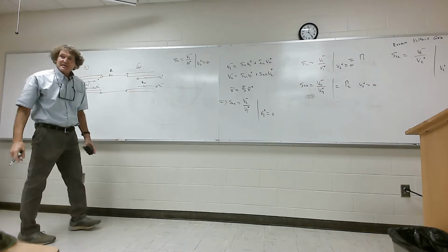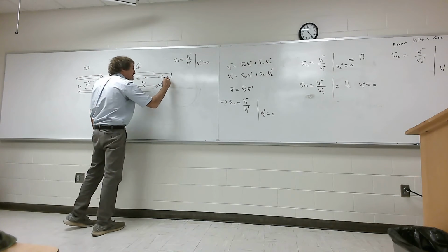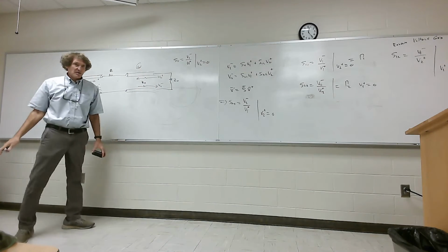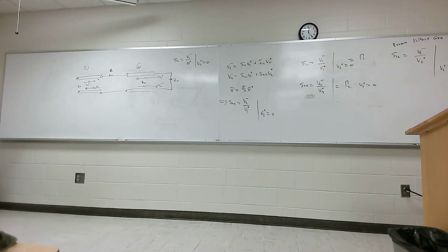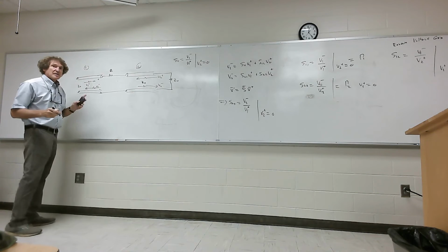Now, here's what it means in a nutshell. It means that the load out here is just going to have a value of Z0, so there's no reflections. That's all it is. Y'all follow me? That way you can't have a V2 plus if nothing's reflected. Everything passes through. When I take a look at this, it's really what? Now just look at this.